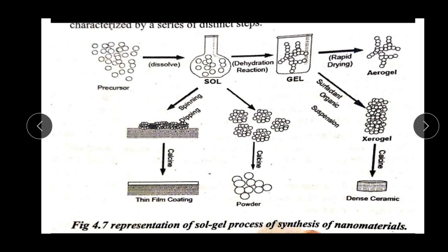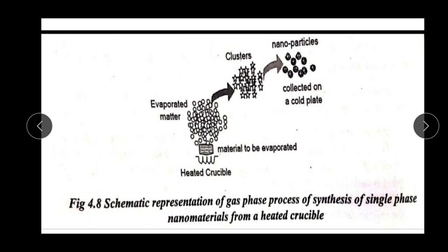The sixth step is densification and decomposition of the gel at a high temperature, around 800 degrees Celsius. The pores of the gel network are collapsed, and the remaining organic pieces are volatilized. Hope you understand how the sol-gel process works.